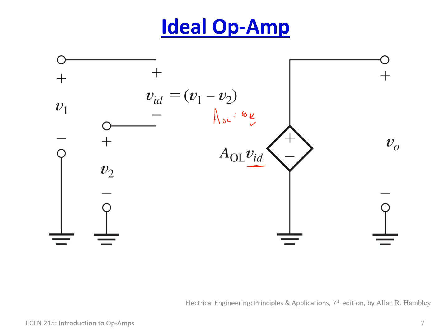And, of course, again, if there was output resistance, it would be here. And R out is, in this case, equal to 0 ohms. So now that we have our circuit model, let's investigate using it in a configuration, because having what we call the open loop model of the circuit really doesn't do us any good. Any small difference here, I mean microvolts, nanovolts, is not going to matter. Anything is going to cause this thing to go to infinity.